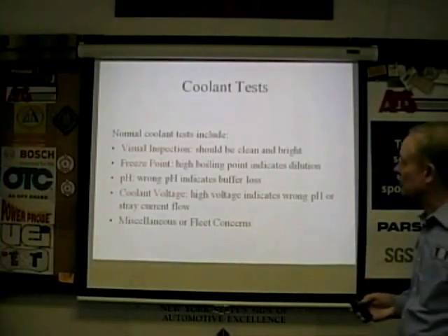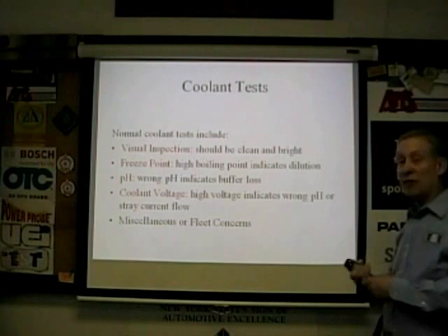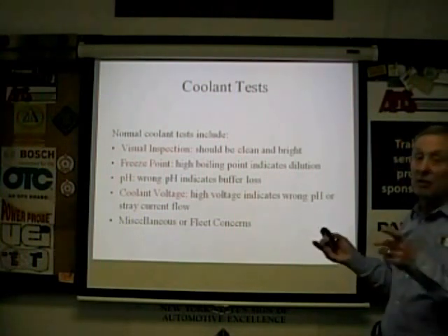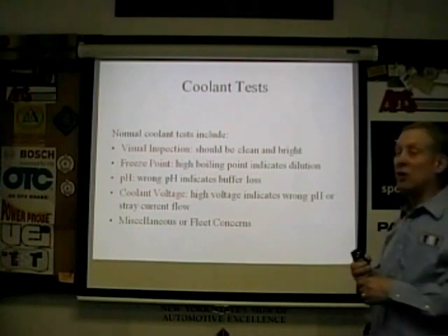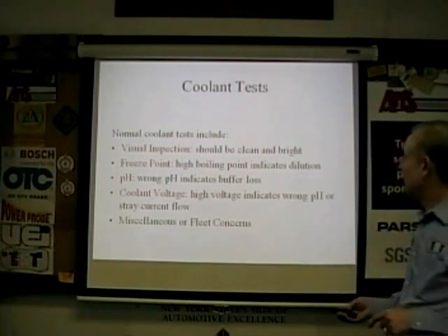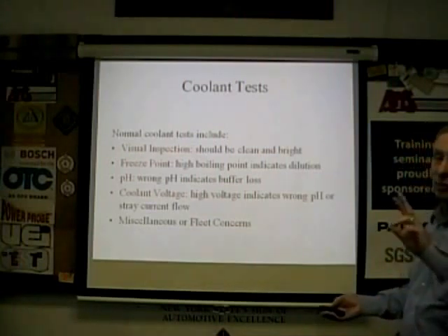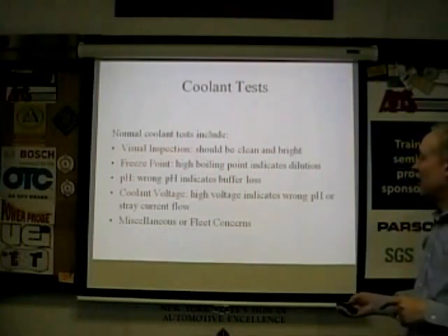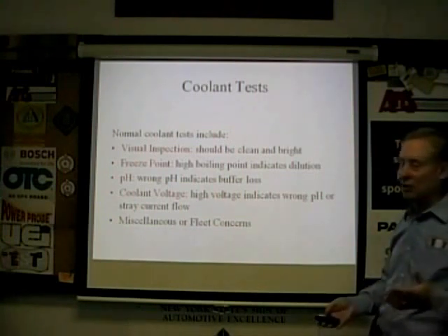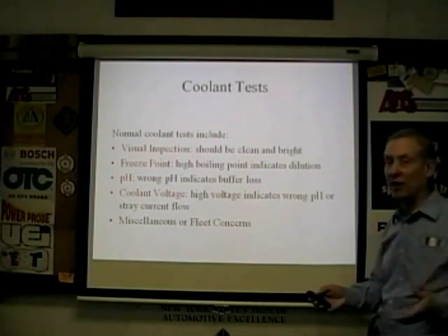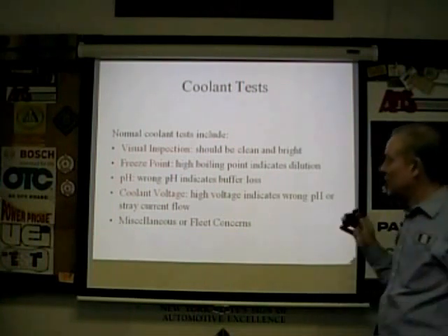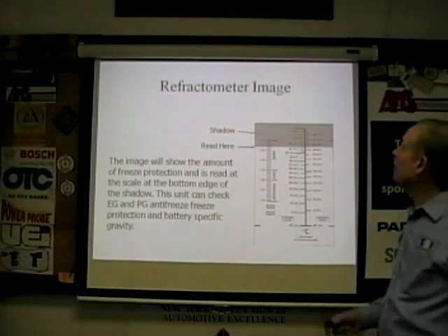Coolant tests: visual inspection, freeze point, pH. You have to use the strips or a meter, they make meters. Coolant voltage in the system, and you have to make sure that you don't reverse the leads. We'll get into that. And then there are miscellaneous or fleet concerns, specific to a manufacturer or the way a car is operated. Police cars get different duty, or ambulances. You have to understand your market.